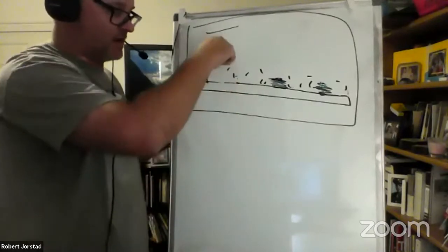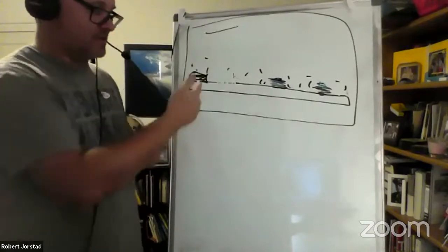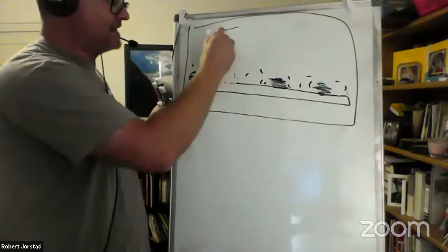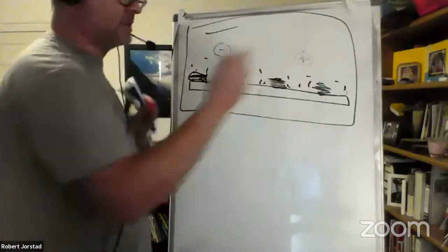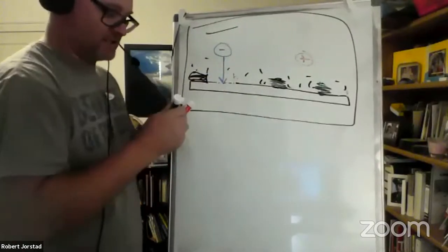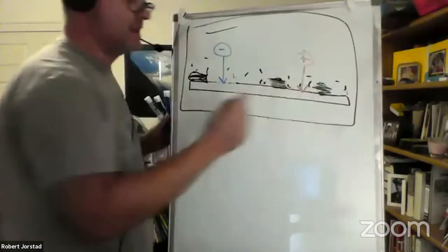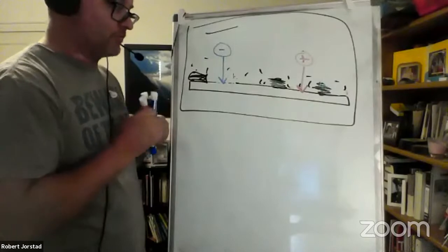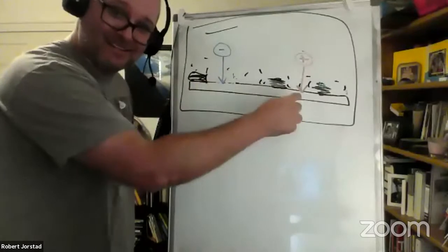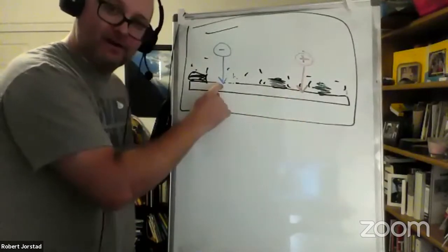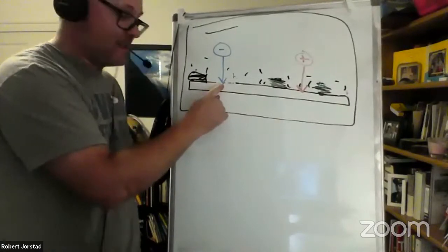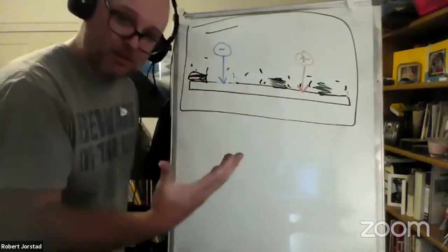And then the other thing you could do is implant ions into here. So you could have metal here to make contact. The idea is you might take ions, either positive or negative, and if you jam them into here, phosphorus and boron are the two common ions for silicon. If you do that, you could create regions in the semiconductor that are better conducting. By implanting these ions, you change the rho. So you could change the conductivity and make this section conduct well and make it connect to this contact, so you can blah, blah, blah, blah, blah.